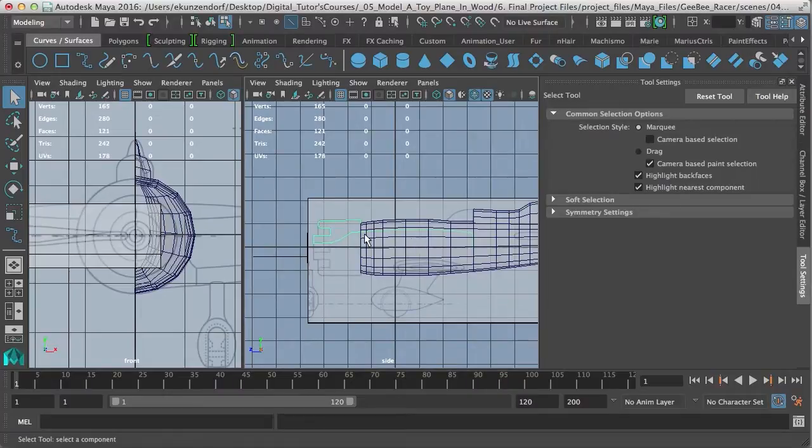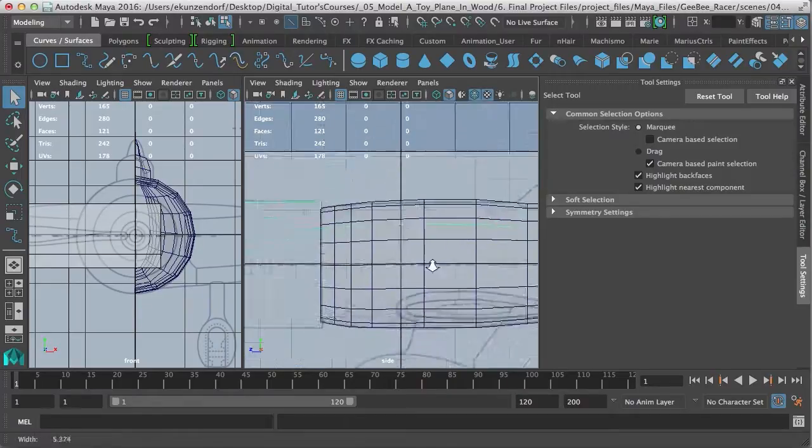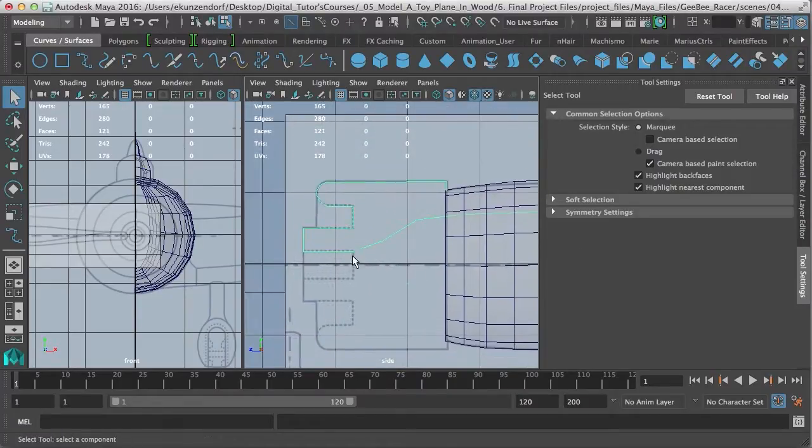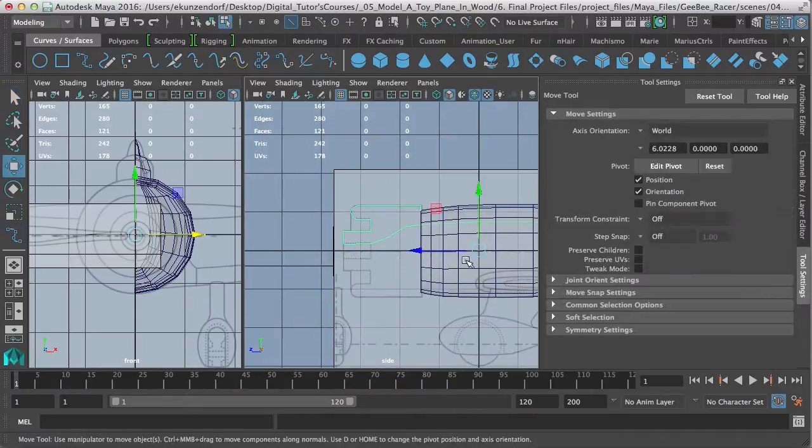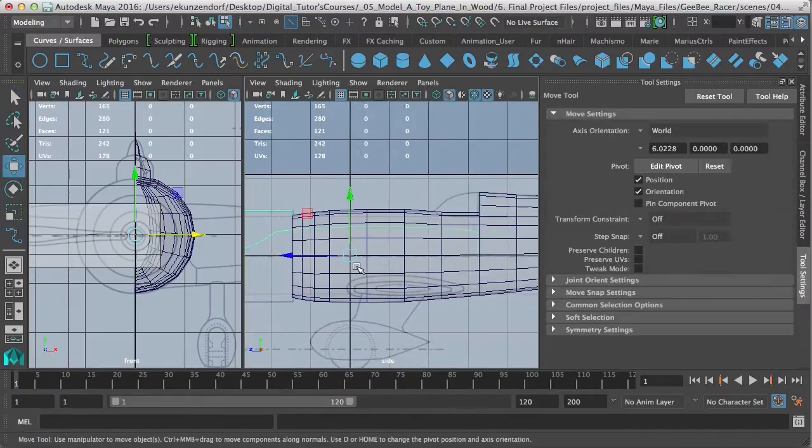So point being that we're going to go ahead and do this. We're going to rotate it like so. If you're not going to 3D print it, it's much, much easier simply to close this off like so. All right, so I'm going to hit W. There's my point. Now, when I'm rotating a curve, very rarely do you hit exactly on the right line. So I'm going to pull down the D key and the C key, and I'm going to middle mouse drag along this curve until I get to the end point. And that's going to be what I'm going to rotate on.